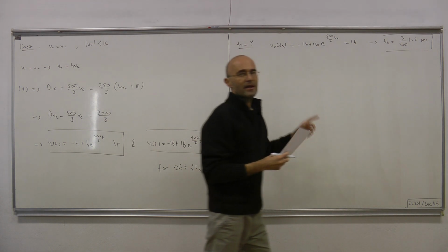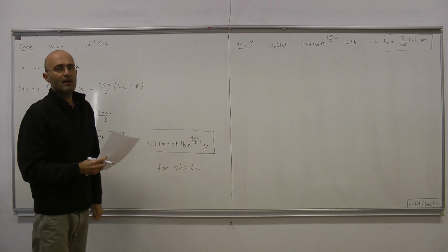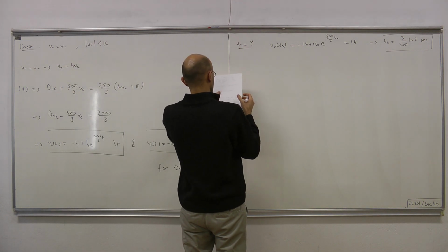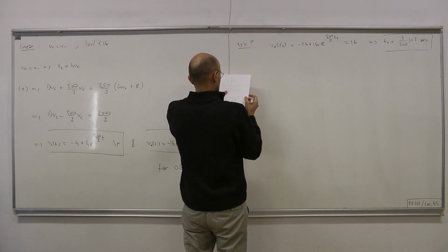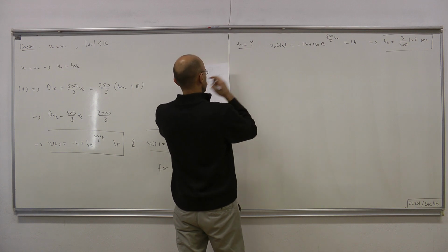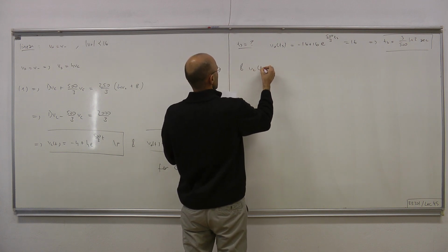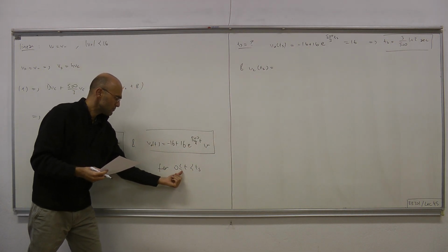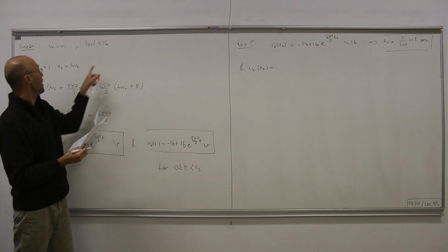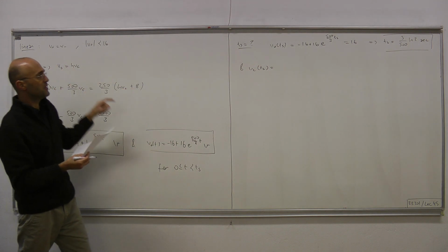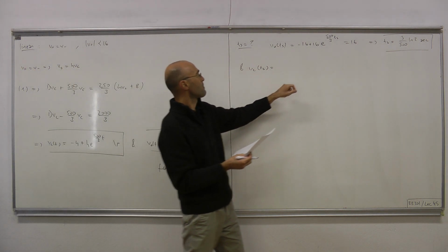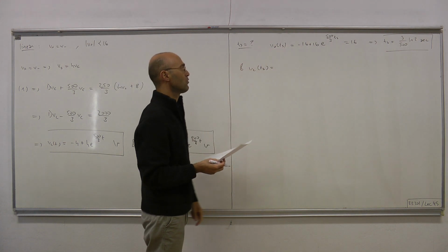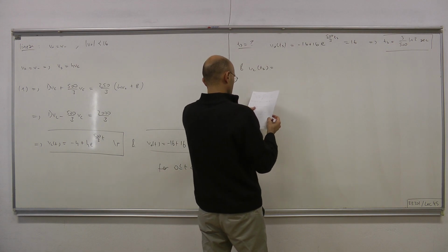Okay. At that time, the op-amp has to leave the linear region. So that's Ts, and since between 0 and Ts, V out is 4 times VC, therefore VC(Ts) must be V out(Ts) over 4, which is 16 over 4.